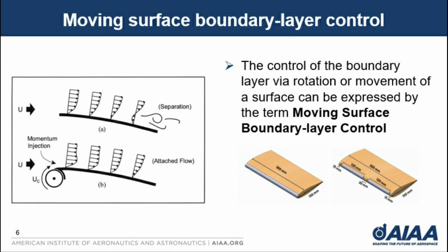In the present study, a moving surface boundary layer control is considered a method to improve aerodynamic characteristics and to delay the transonic change. A flow control was carried out considering a piece of the upper surface of an aerodynamic profile that will move with a constant speed. It is about delaying the transonic change because transonic flight is characterized by the appearance of a local supersonic region on the suction side of an aerodynamic profile, ended by a shock. This shock leads to a loss of overall pressure resulting in additional drag.